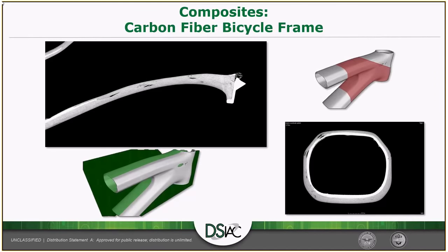And here's a representative example of composites and a different material like a metal or an aluminum, the interfaces, and what information you can get from CT scanning there. If you look at the bottom right image of this bicycle frame section, you can see the metal and composite interface. There is a voiding on that surface, which, when this does get put under a load and tested, you can predict is where your failure might occur. So you can have this information ahead of time, which is very useful. In the post-test, you might not know if that was there ahead of time if you didn't have a scan of it or if you had the cross-section. So again, it's just a nice tool to quantify all these features before you go ahead and start your testing.